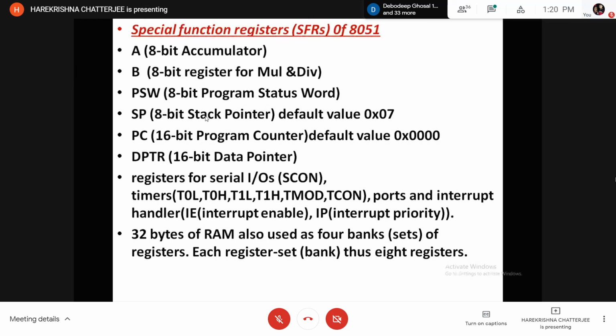In total, 16 bits can obviously denote it, because internal program memory can be accessed by a 16-bit address. That's why the program counter is 16-bit. 12 bits of it will be used, because internal program memory size is 4K, which requires 12 address lines. So if the memory pointer register is 16-bit, then it can accommodate 12 bits. No problem.